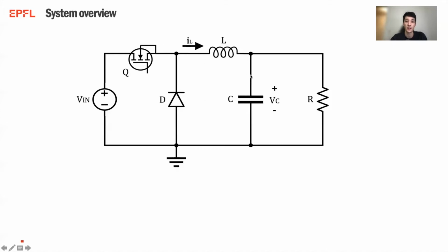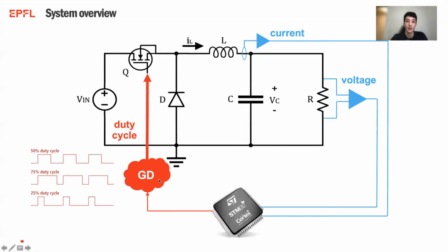The remaining components are here to make this electronic circuit work, but also to filter out some of the ripple that will show up here due to this high frequency switching activity. Very well. All of this is usually done in closed loop. And if you need to close a loop, you'll probably use some form of a computing device, illustrated by this microcontroller. Of course, you could have something else in its place. For example, a dedicated, specialized analog circuit, which is really common in the field, or even an FPGA. But we'll focus our attention on microcontrollers.